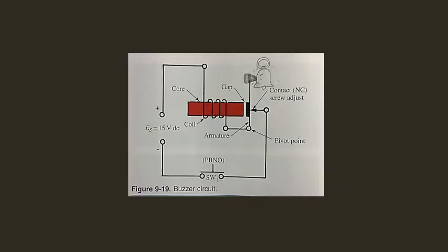Lesson in safety. The circuit breaker is installed for safety. It prevents overloaded circuits and the danger of fire. The breaker should never be disabled or bypassed. If the breaker opens a circuit repeatedly, locate the condition that is causing the excessive current and take immediate corrective action.